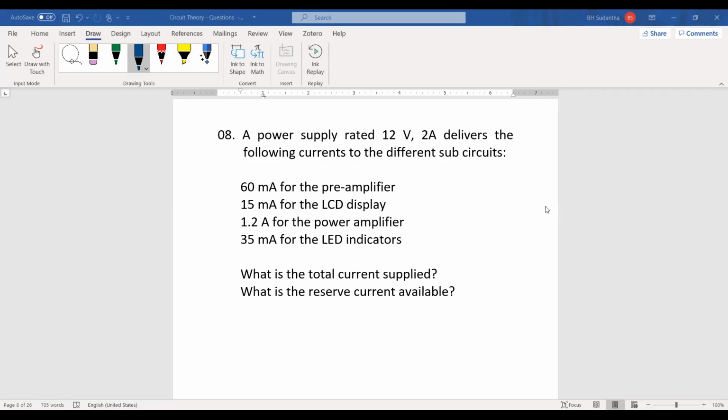All the voltages developed across the components in a particular loop, you can add together, and it will equal the main power source value. And KCL, the current law: the total incoming currents are equal to the total outgoing current.